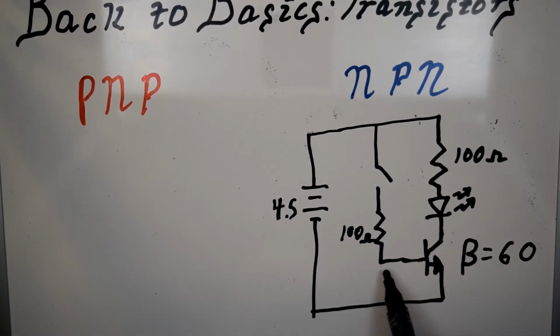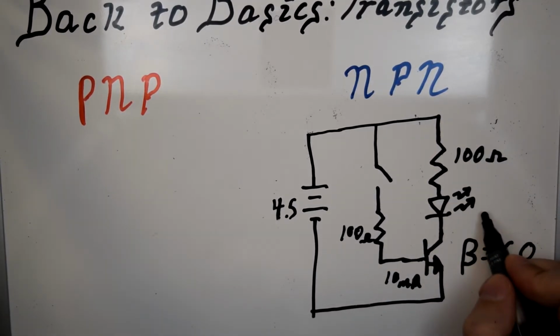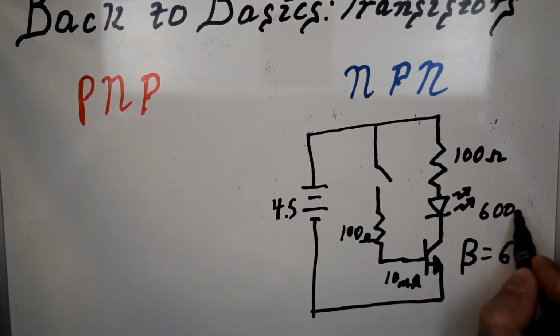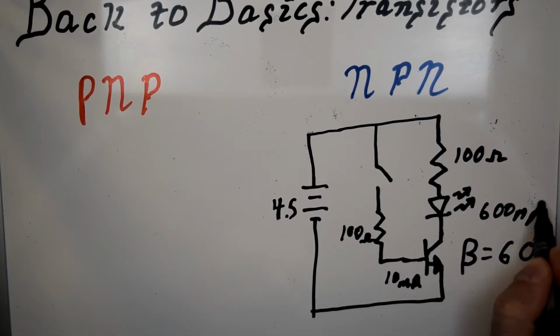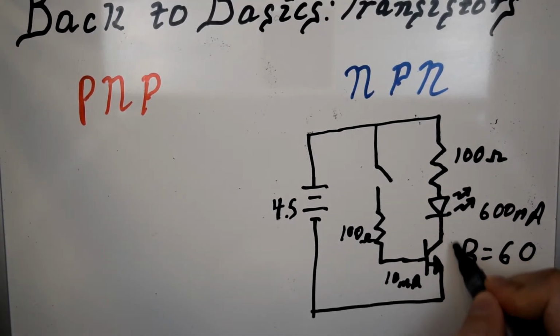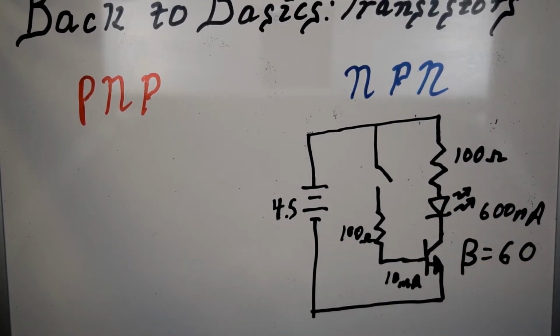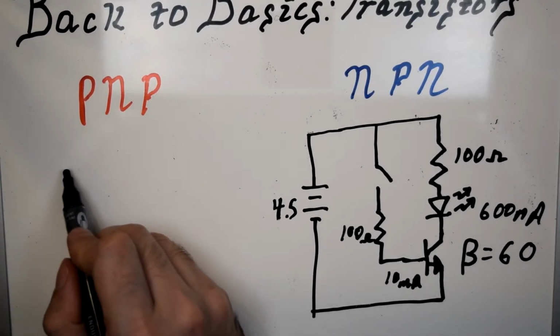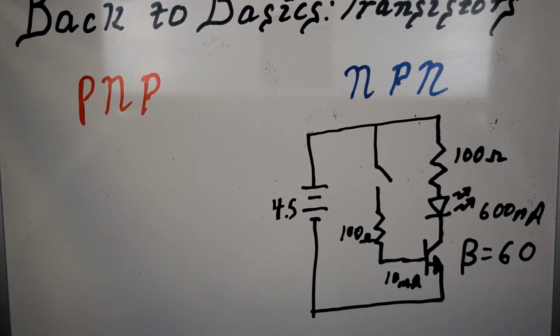So let's say we induced 10 milliamps here, we'd induce 600 milliamps from the collector to the emitter. Now it's the same kind of idea with a PNP transistor, only I'm going to just quickly re-verify with my...